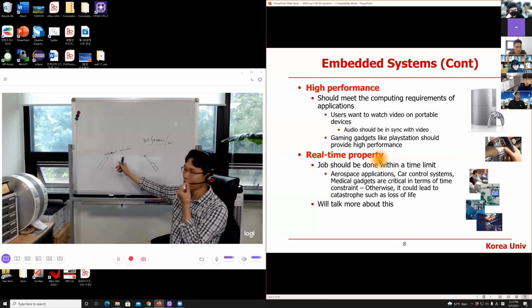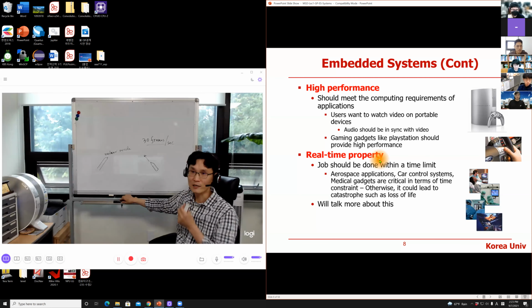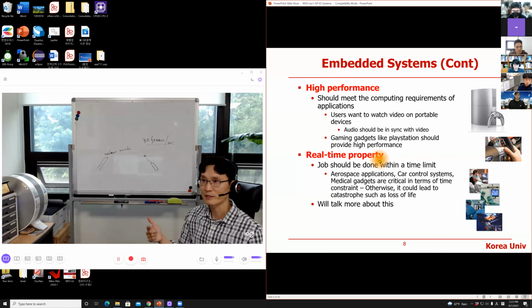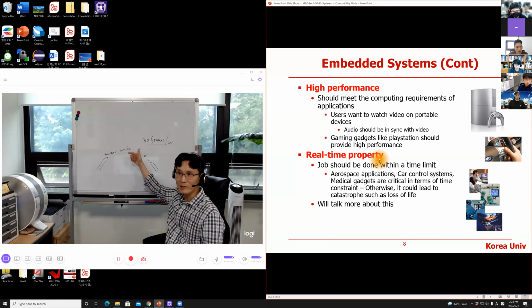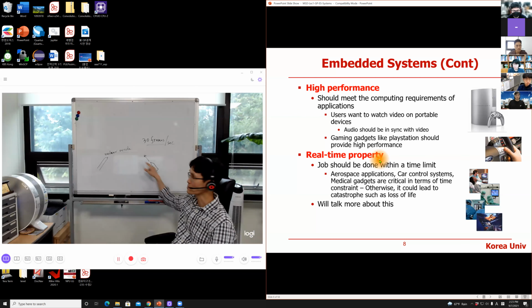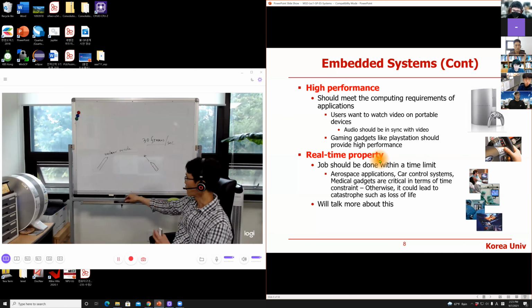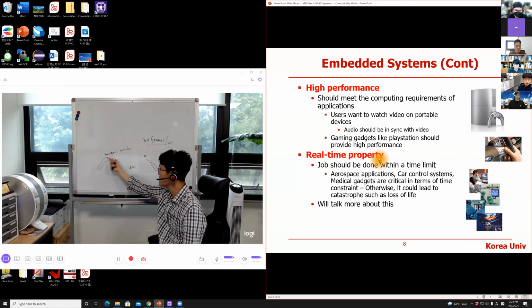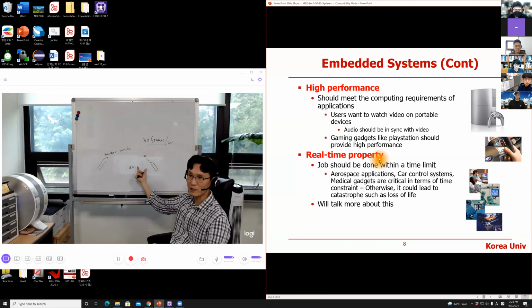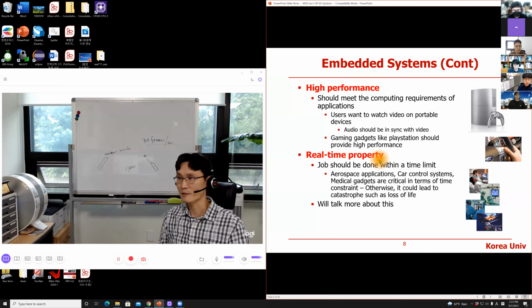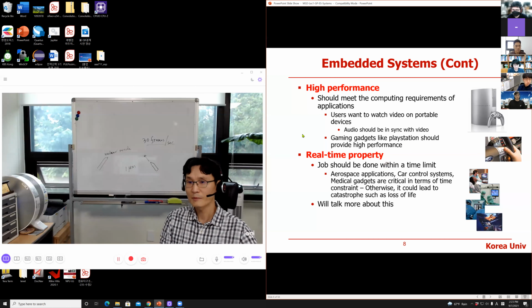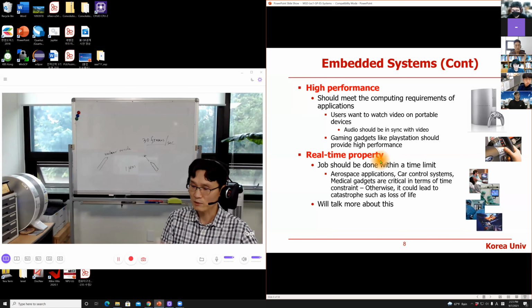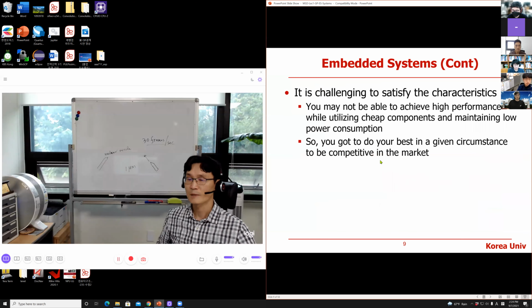It is a moving target, right? While it is flying, it is changing position every microsecond, and this one is calculating its position. So there is a hard time limit. Within 1 microsecond, you have to compute the new position of the target. If you miss this deadline, then you cannot hit it. So the real-time system. Some embedded systems require that real-time property, depending on applications.